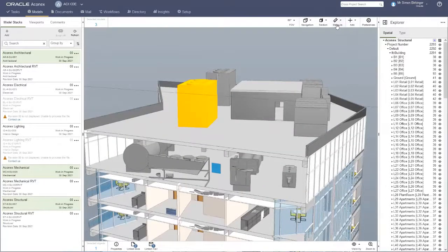There's also the possibility to add sections and measurements to your model. So let's choose this measurement tool and then choose either the distance, plane to plane, or a multi-point measurement. So in my example, I will choose the plane to plane, select those two objects, like this, for example. And then I can measure between those objects, which is 8 meters, 53 centimeters. And now it comes to the point where I can make my communication a bit easier and more meaningful with the help of the 3D information for the participants of my message.